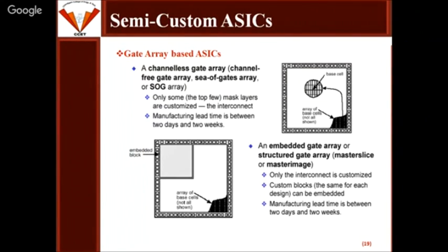Basically, first of all, we go for floor planning and placement. We have placed the devices, then we go for the routing, and after that we go for the compaction. Suppose we have done the placement and then the routing, and in routing we are facing a problem. We are not able to connect the devices. Then again we have to move back to the placement. So after the placement there is routing, and then there is compaction. In general, compaction means whatever channel region is left unrouted, not utilized by the routing, we compress the whole chip from all the directions.